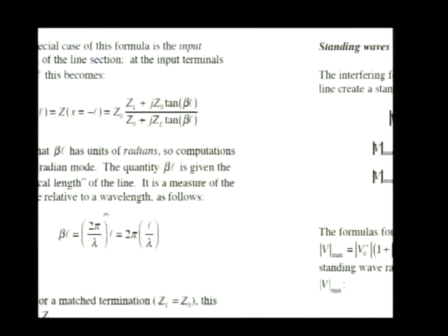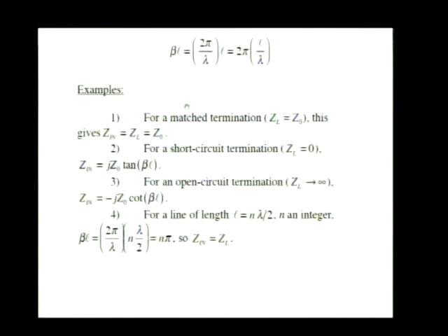The reason I stress these two facts so much is because, remember when we were talking about the low frequency parameter sets? How were they defined? How would you measure them? You'd take your 2-port device and you'd either open circuit one of the terminals or short circuit one of the terminals. I said that's not a very good thing to do at RF. Well, here's one thing you can see as a reason why that's not necessarily such a great thing to do